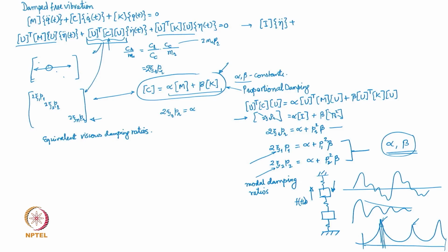So there are different ways of taking care of this, but we harp on one important assumption here, that in most mechanical systems, most rotating mechanical systems, we do not really encounter, except in some cases, frequencies so high that many modes are crossed over. If you are working in this particular frequency range, the contribution from higher modes is negligible, so they do not contribute much to the response. So it suffices for all practical purposes to use this approach to get alpha and beta. Once you get them, then you can get the decoupled governing equation of motion.